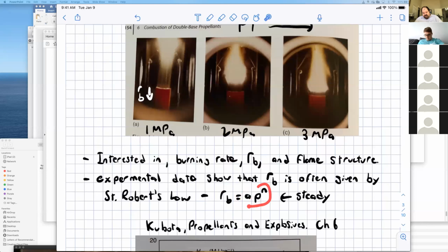After you derive that, you can relate A to thermophysical parameters of the propellant, and N to the order of the gas phase chemical reaction mechanism. Now, this constant in the predicted N is way off of actual physical values, but nonetheless, this analysis is a very good fundamental analysis for understanding how these propellants burn.